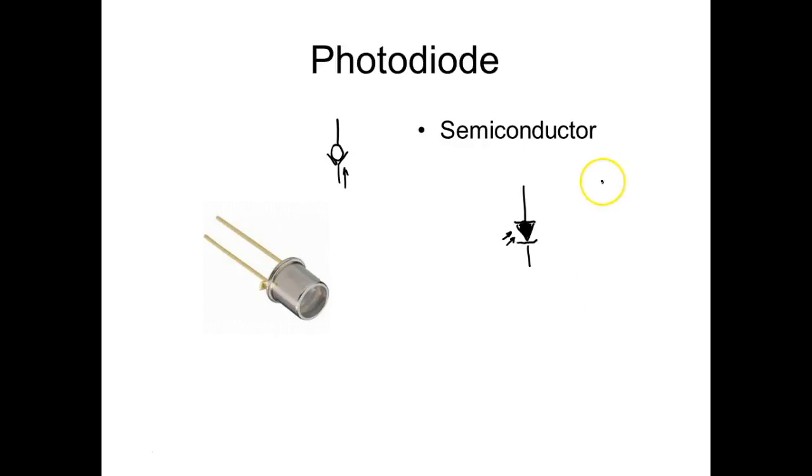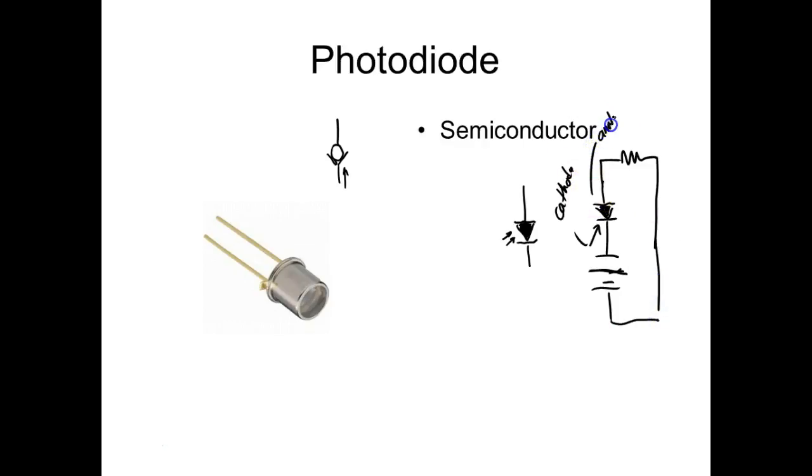So what we do to make the diode actually conduct is we would come over here and let's put a resistor right there. And what we would do on our DC battery, if I pointed the negative toward this guy right here that we call the cathode, and then I pointed the positive toward this guy, which is referred to as the anode, then it would let it conduct. Current would flow in this direction right here, against the arrow.